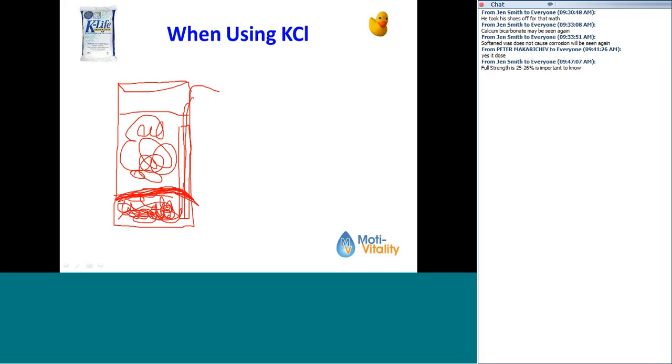There's a very, very scientific way of repairing this if that happens, and it's called getting a broom handle and banging holes down through the salt pile in that brine tank and breaking up this dome and letting it drop down. It's a very scientific method of doing it. A crowbar works really well too. Hammer it down into it and break up that salt dome and let it drop down in there.